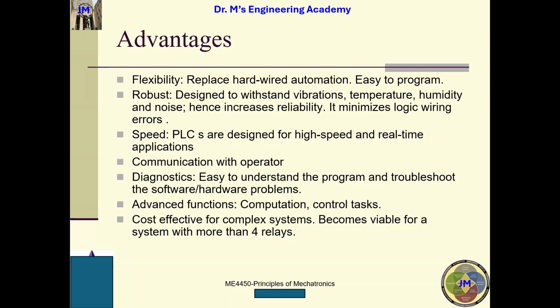Before the PLC appeared, people used control relays and a lot of wiring. You wire the system with your hand, using physical wiring, the hardware, and put things together. It's very, very easy to make errors. For the PLC, all this manipulation is carried out in the microcontroller. So as a result, it's very, very robust.